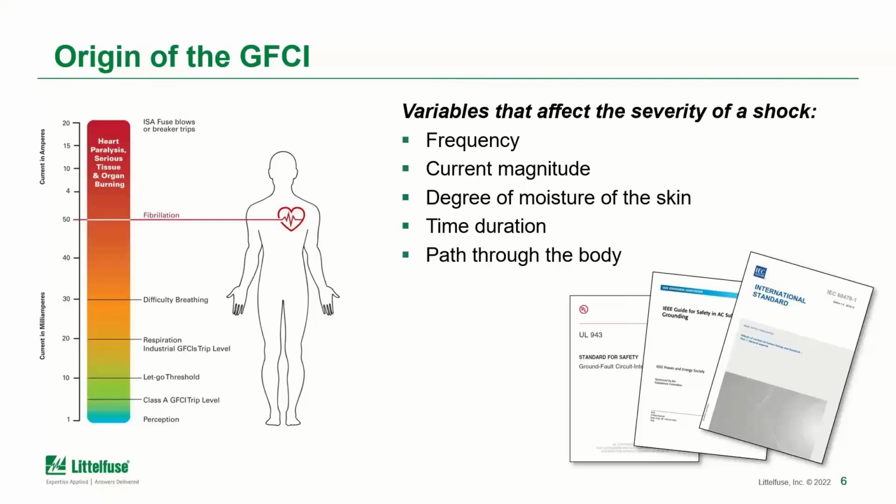Second, affecting your ability to breathe, your heart, and serious damage to the nervous system did require shocks of greater intensity than those required to just produce ventricular fibrillation. So if accidental shock currents can be kept below the fibrillating threshold, the probability of death can be significantly reduced.